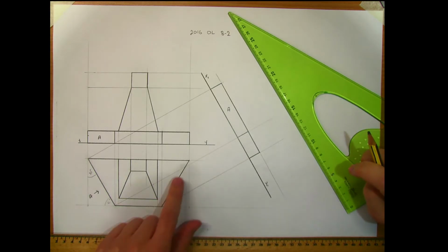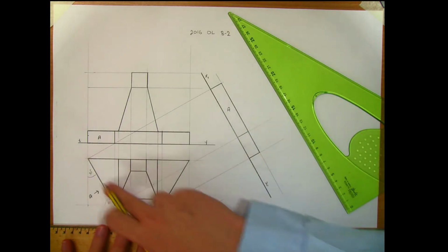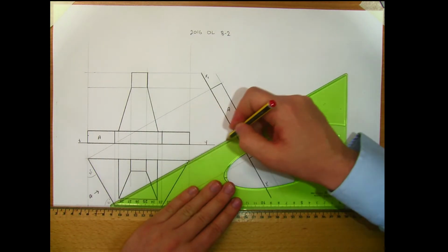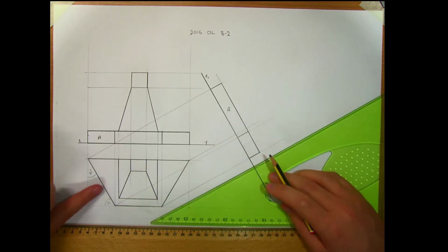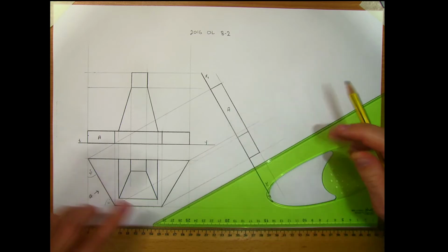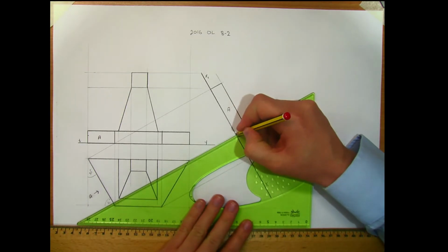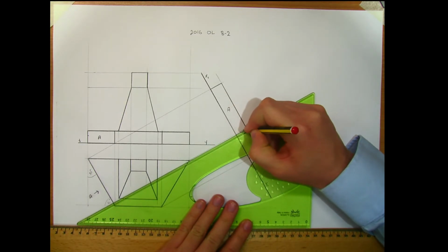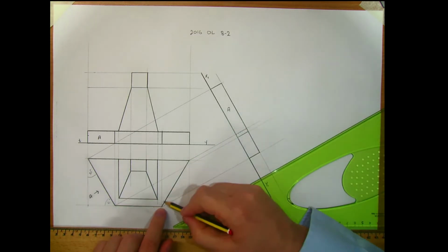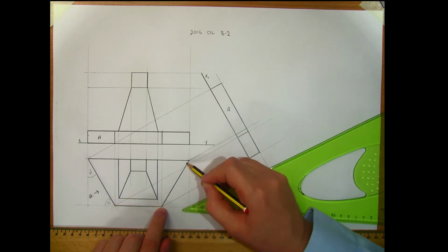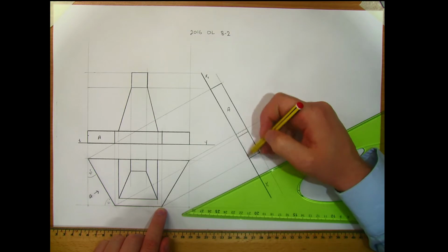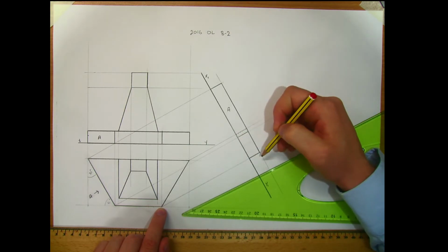Okay. Then after that, we've got lines here on the base at the back. So we'll project this line up along. Now, when we're looking in this way, I can't see this corner. So this corner back here will be a hidden detail line, so just a short dashed line coming up along here. These lines, we also can't see them, and by right they should be hidden detail, but they're hidden detail behind these lines, so we don't need to mark them because there's a solid line in front of it.